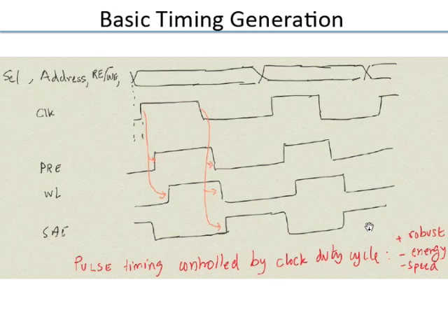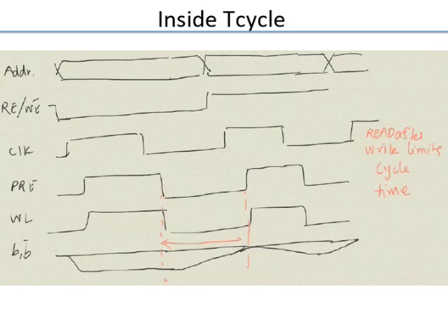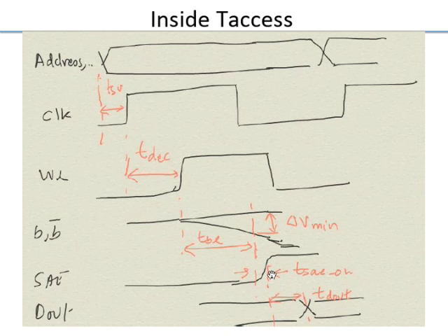Why is it robust? Because say there is a problem that maybe your timing generation was messed up. Basically what you want is that the SRAM enable signal should not come too soon, because if it comes too soon, there is a danger that the voltage is not enough for it to pick it up properly. If it comes late, functionally it is okay, but you're losing timing, you're wasting time. So that is the thing.